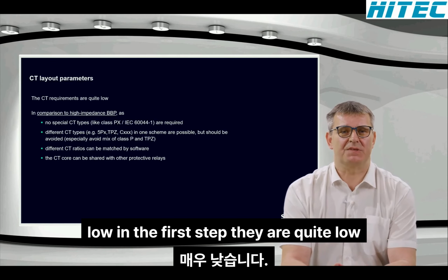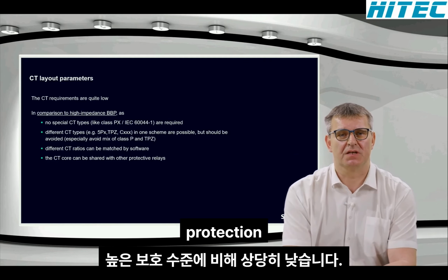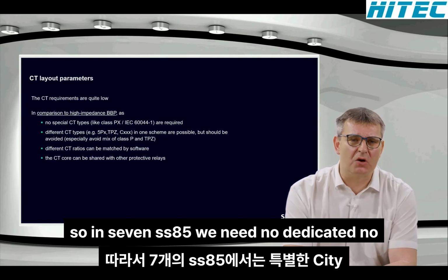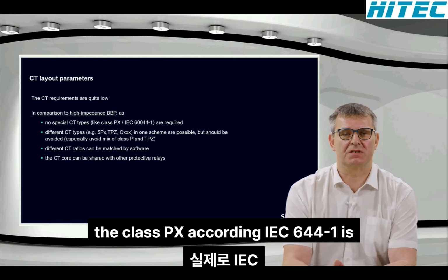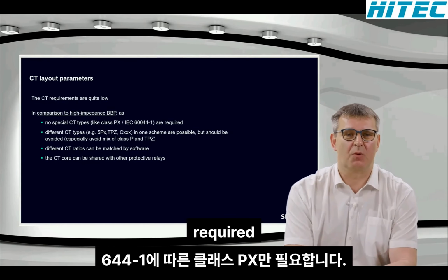In the first step, they are quite low in comparison to the high impedance busbar protection. So in the 7SS85, we need no dedicated, no special CT types, whereas for the high impedance busbar protection, really only the class PX, according to IEC 60044-1, is required.